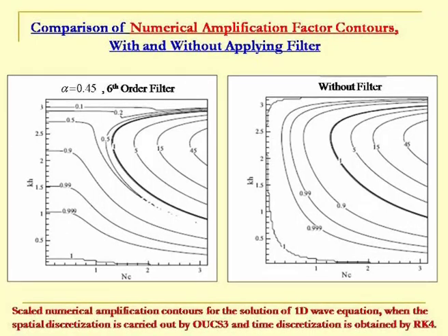So this is something we have to realize, why filter is so often welcome, because most of the numerical problems originate from the high wave number region, and if there are problems, application of filter actually removes them quite drastically. However, you may lose accuracy of the solution. That is another issue that we have to keep in mind.